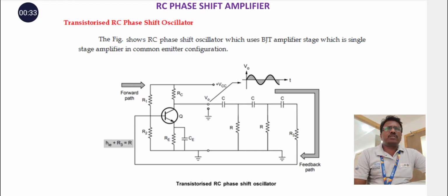First let me ask you a simple question and discuss. Can an oscillator generate an AC signal without giving any input signal? The answer is yes. Unlike an amplifier, which requires an external input signal, an oscillator generates its own AC waveform by converting DC energy into AC energy. That is why oscillators are called self-generating electronic circuits.